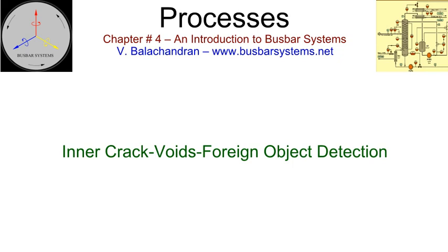In the ultrasonic test, a beam is directed towards the object through a couplant. When the beam meets a discontinuity, it is reflected back. The study of the incident and reflected beams diagnoses the size, depth, and shape of the discontinuity. Needless to say, this procedure also requires skilled personnel to handle the equipment and interpret the results. For conducting this test, accessibility to one surface is sufficient.